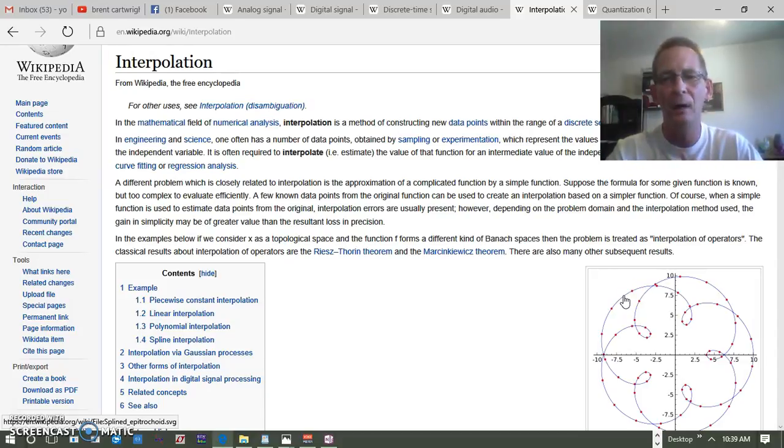It's a guess. There is no way to actually know exactly what it is, so it's always worked out to a best guess. And so the way that's dealt with most of the time is: the more samples, the better. That way the interpolation between samples is smaller and smaller and smaller, and you have a better representation of what's happening between the samples that you captured. And that's a very simple understanding of the process that's happening.